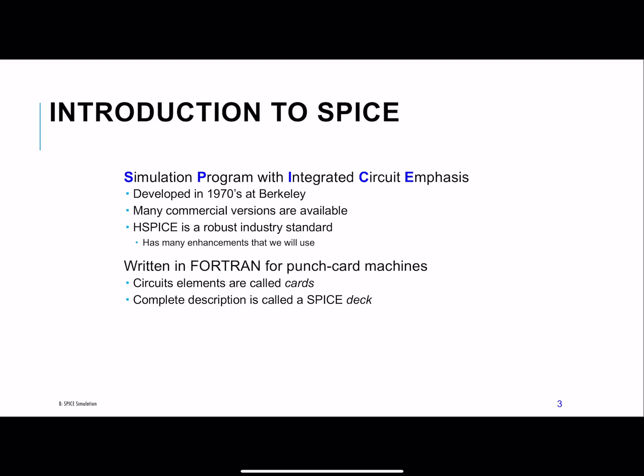This is a program that is developed to do analog level simulations of circuits, and there's a bunch of versions available for the project. For our project, I've suggested we use LTSpice, but there are other versions: PSpice, HSpice, and Cadence has its own version called Spectre. So there's a bunch of different pieces of software that do the same simulation.